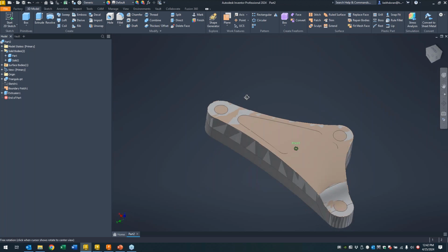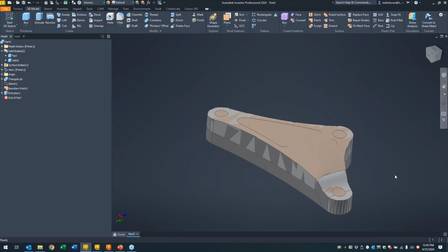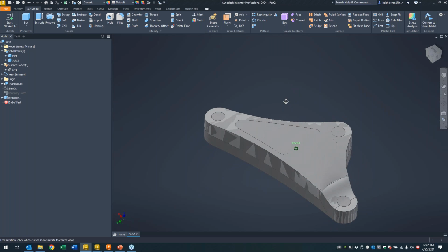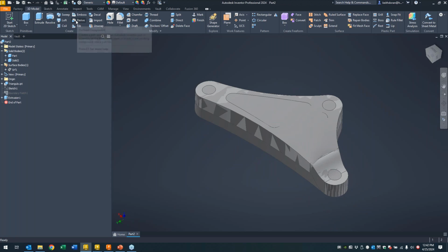And again, the general idea here is that if I've already got a stock object or I've done all these outside manipulations to this shape, I now have a part that I can then start to work with for doing all the interior cuts of that surface. And again, I could add any other number of features to this. So if I needed to, put a tab on it or other flat surfaces on this, again, it's really up to me at that point how I need to manipulate that shape. But again, all I did there was I used the derive command, and then I stole some geometry off the top and some geometry off the bottom and used that geometry to create a new solid.